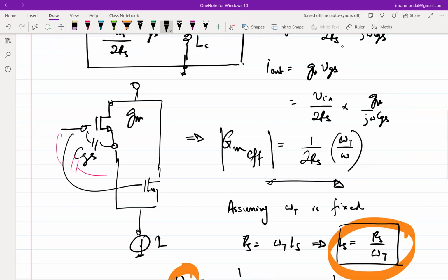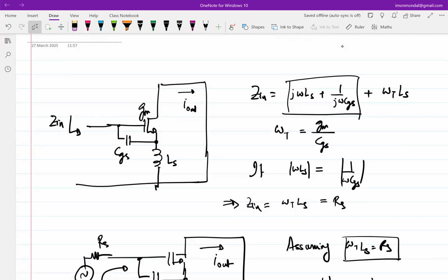So here, all we can do then is place maybe an inductor here. I do not want to place an inductor in series with LS because that's going to move many of the other things. Your match is dependent on LS, so your resonant frequency is dependent on LS. Whenever you have some component which controls multiple variables, it's better not to touch it once you have fixed it. Try to introduce one component which can control only one variable.